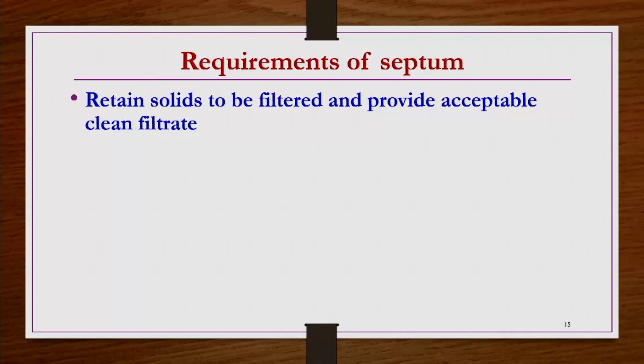In some processes the volumetric flow rate of filtrate collected is in general very small, something like 10 power minus 3 meter cube per minute. If the filtrate volumetric flow rate is that small, that operation cannot be feasible at industrial scale in general.